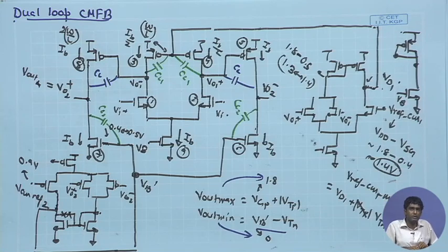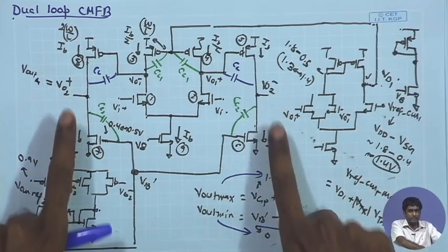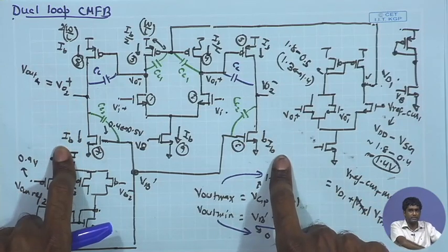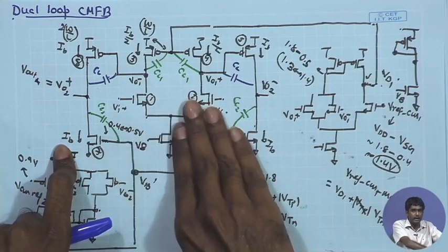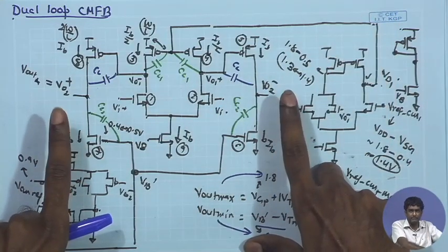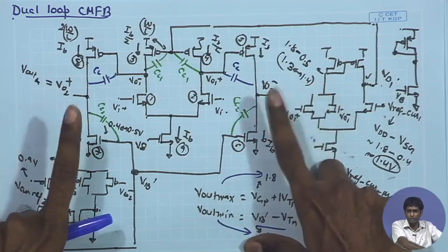For example, if you have to compensate the differential feedback, consider the capacitive division. As I said last day, your differential feedback has the capacitive division. As a result, the loop gain is A1, A2, that is GMRO square order, times the beta factor, which is small, maybe 1/30 or 40.